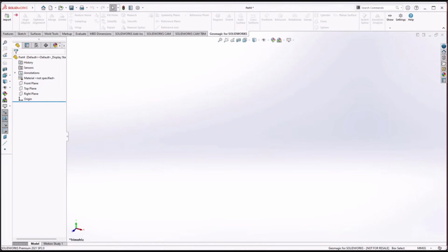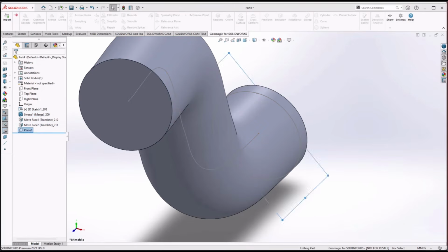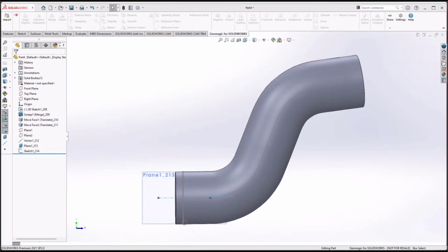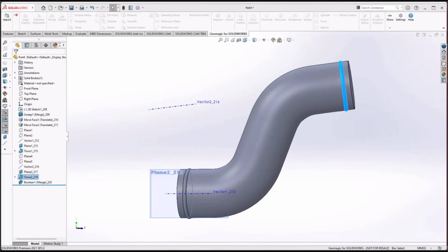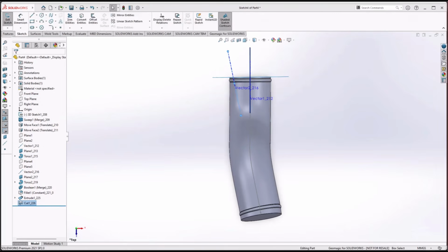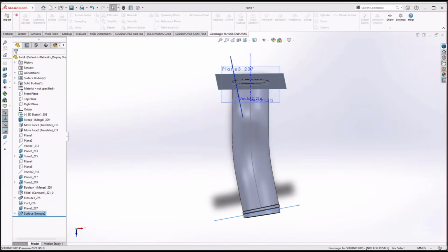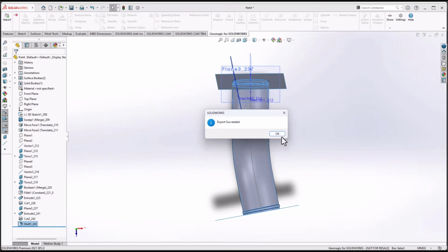And what we do is we call it LiveTransfer because you have to have both SolidWorks and DesignX on the machine at the same time. And it streams over while they're both open. So it's streaming that data into SolidWorks live, on the same machine. And it's building all of this stuff over here as native entities. So we'll just give it a second. It'll pop up and tell us that it's completed. You'll see here. Right there, export succeeded.